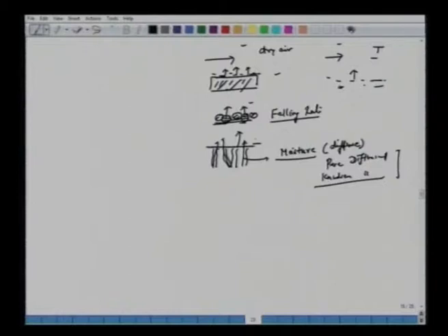All right. So now we are talking of the hidden moisture. These are the surface moisture. These are the moisture which comes from within, from inside. So we have seen the third type of falling region where the rate was non-linear. Here the rate was linear. Here the rate was constant. And of course before this we talked of the initial adjustment, where the solid gets warmed up or comes to equilibrium with the air temperature.